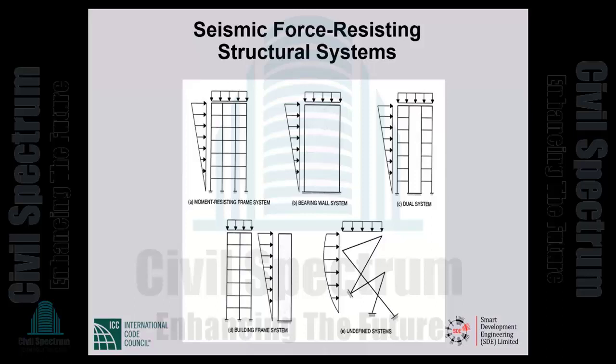In that type of a system, something very important is deformation compatibility. You have to check and make sure that the gravity frames can continue to carry full factored gravity loads as they deform together with the seismic force resisting system all the way up to the design earthquake displacements.